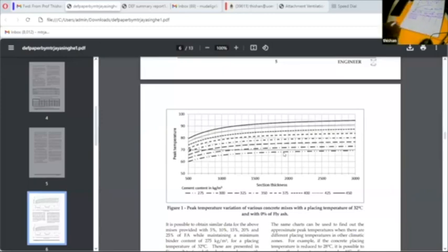because I want 40 megapascal. I'd like the cementitious content to be more than 400. So I'm using 120 fly ash. If you look at the ratio, 120 divided by 420, 120 divided by 420 is 18%. So it's okay, right? So I have about 18%.